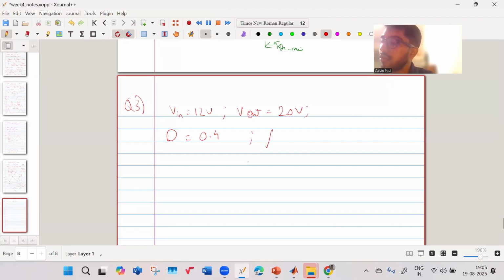Okay. Your switching frequency which you desire is like your nominal switching frequency. Because you must understand this is constant off time control. The T off is fixed. That means your switching frequency can vary. But when you're designing, you consider some nominal switching frequency, and that has been decided as 200 kilohertz.